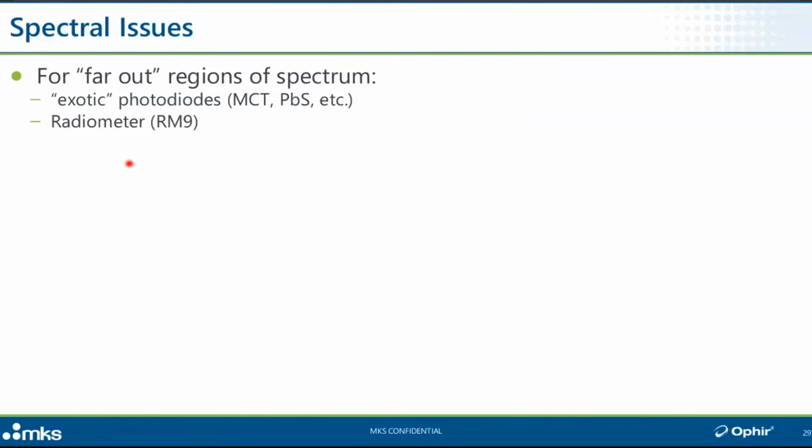In this kind of application, we're talking about a detector that has a spectrally broad response. So we've just addressed one of our issues, and it overcomes the lower sensitivity that such detectors normally have, for which reason we would have wanted a photodiode, by using an optical chopper to modulate the beam, which means we're not going to be using a thermal sensor.